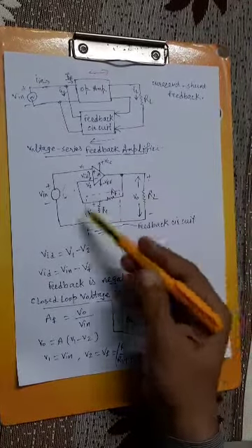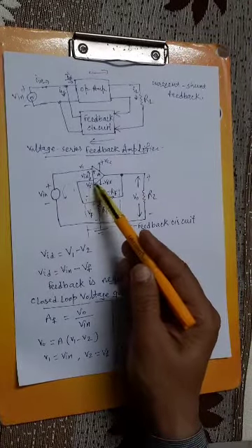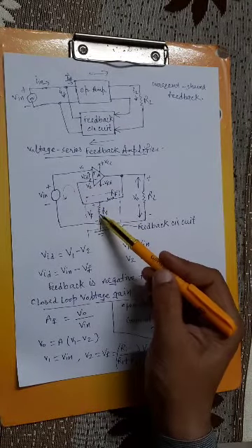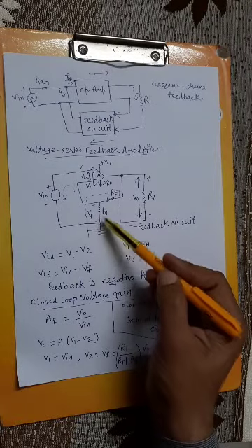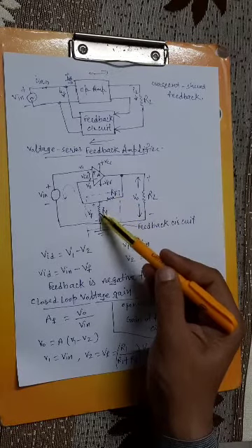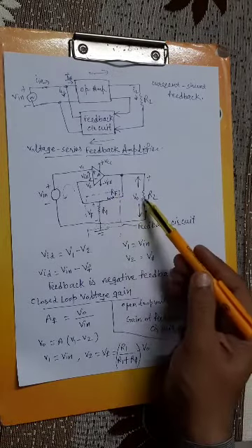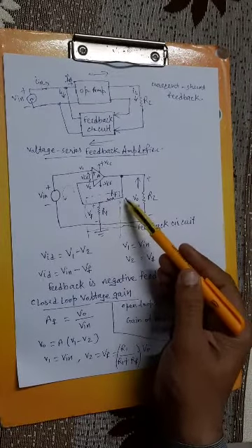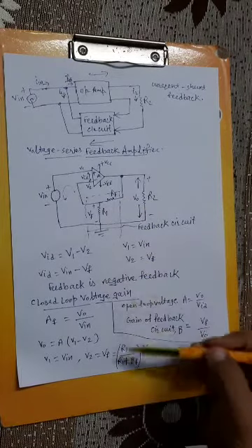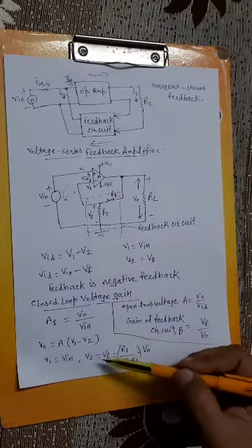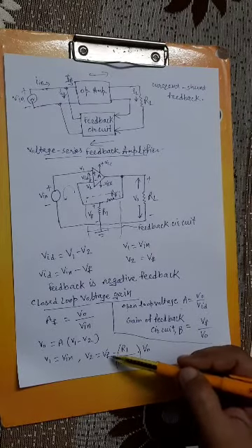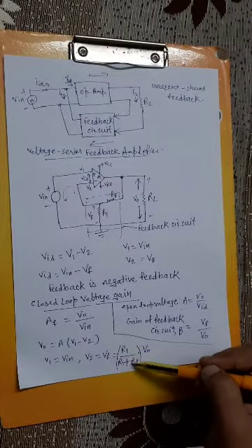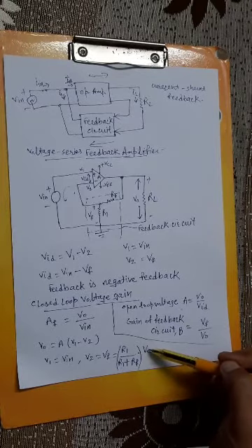Okay, by this circuit, on the V2 side, the inverting terminal, what is the voltage applied? As given by the potential divider circuit, it is R1 by R1 plus Rf into V naught, because V naught is applied in this feedback as an input. So we write that V2 is equal to Vf, and Vf is equal to R1 by R1 plus Rf into V naught.